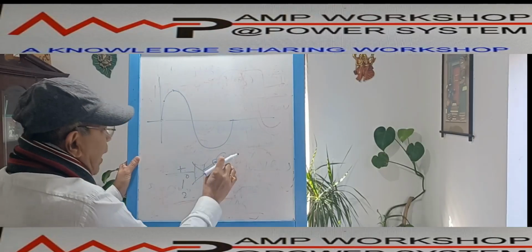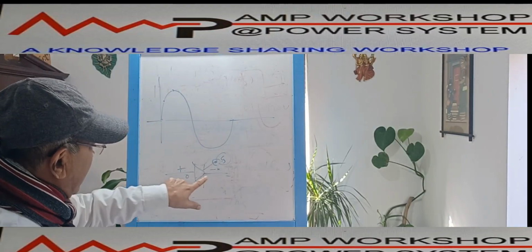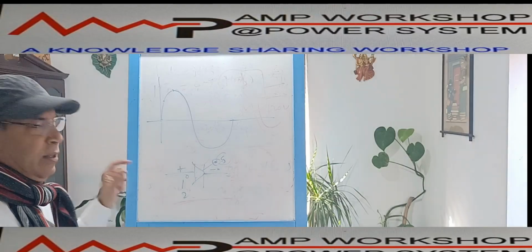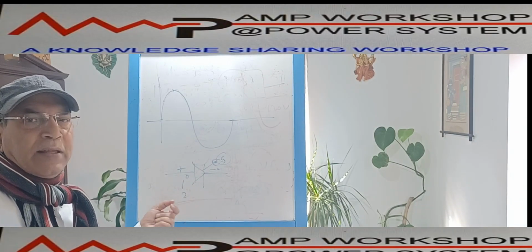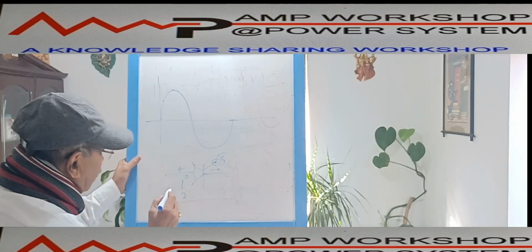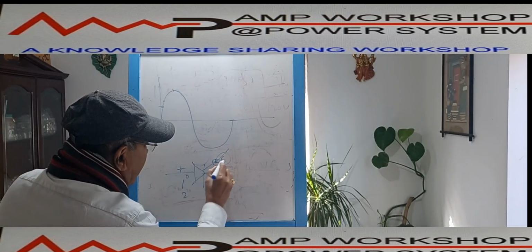It becomes 4, I am not giving any voltage, so it will not conduct. That means though voltage across the thyristor is there, the SCR is not conducting. SCR, silicon controlled rectifier, is another name for thyristor. This thyristor is not conducting. But suppose when the voltage is 1 here, I immediately give a gate voltage.